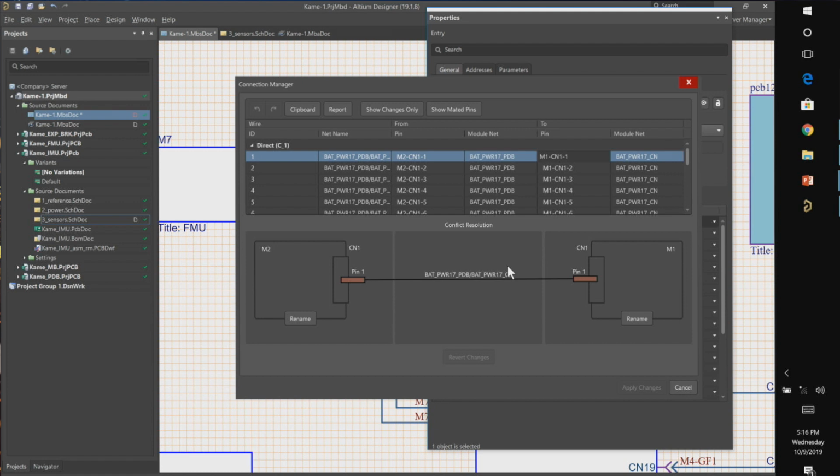Yep. Hand in the back. So I have a question about the interconnects. Is there a way to just have the interconnect be copper on copper, like two things on copper? Sure, as long as they have a pin ID. If there's a notion of a pin, that should be doable. There's a notion of a wire, a physical connection, and then a direct connection assumes something like a pin in a socket type of connection where there's no device, it's just making the contact. So that can be represented.